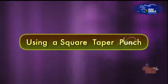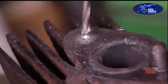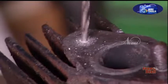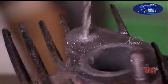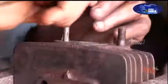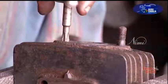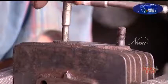Using a square taper punch. Broken studs can also be removed by drilling a blind hole, hole diameter equal to half of stud diameter, and driving a square taper punch into the hole. Turn the punch using suitable spanner in an anti-clockwise direction to unscrew the stud.